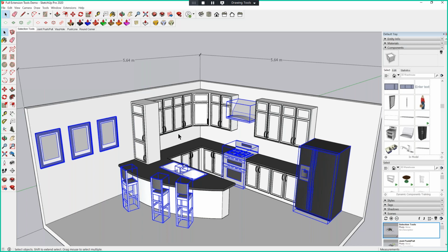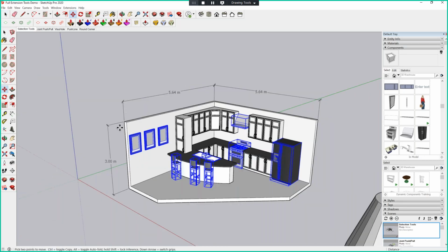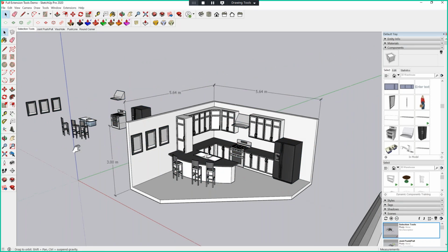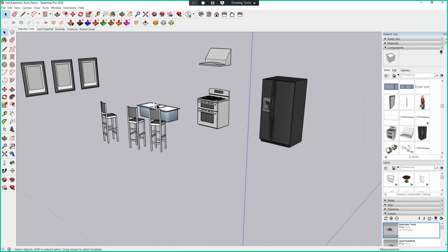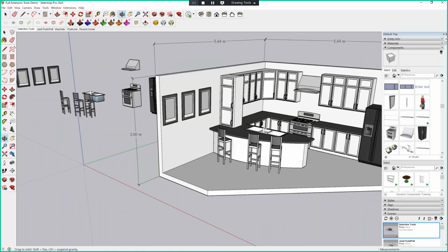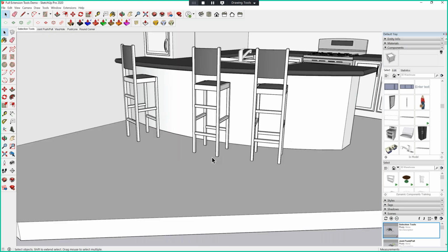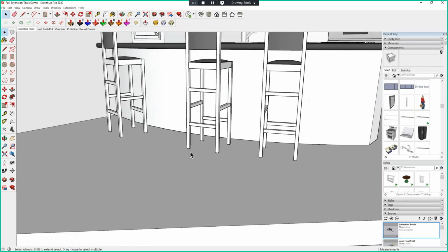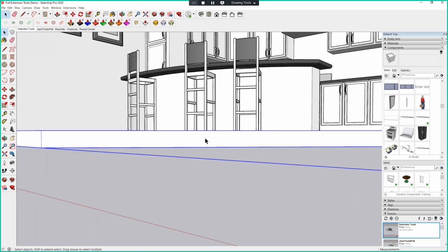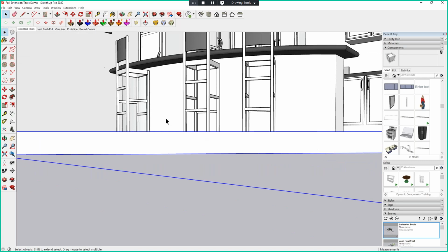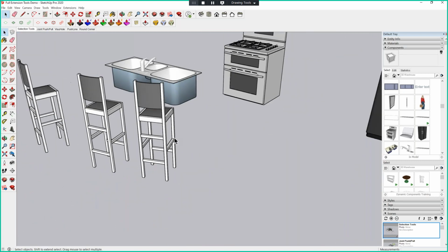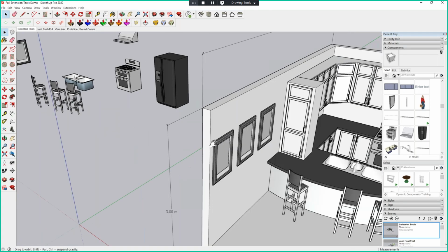So again, it's very fast. You can select your components. You can bring your components out. So I copied it and I bring it out. It's a good practice for this because you can modify your components outside your space and it will be replicated inside your model itself. Example is if you want to build a support for this chair, for example, you want to build a base support here, it might be a few more steps for you to hide the walls just to build a support. It's always good to have an instance outside so you can directly modify this model and it will also change in your workspace itself.